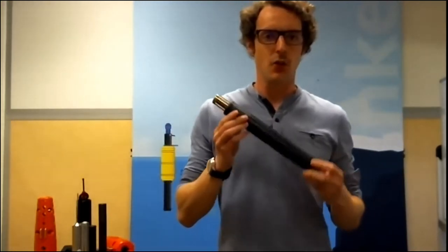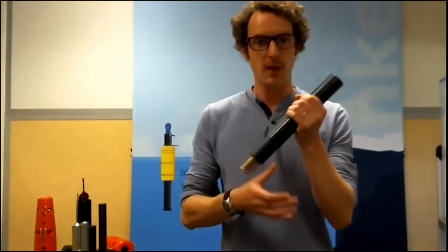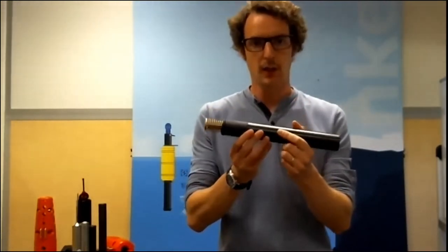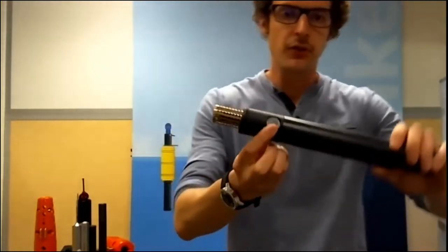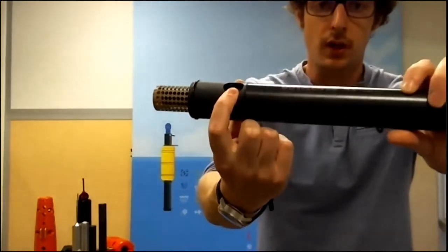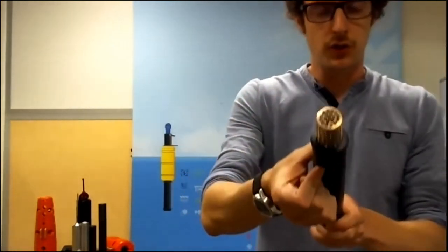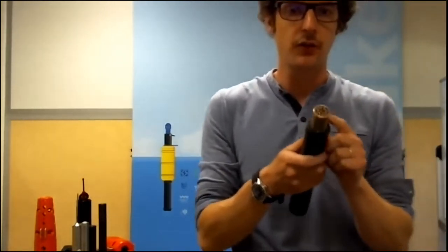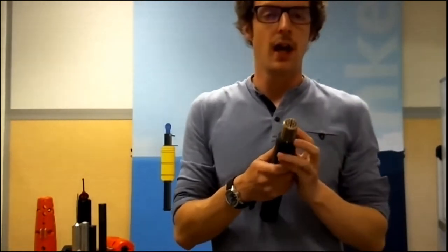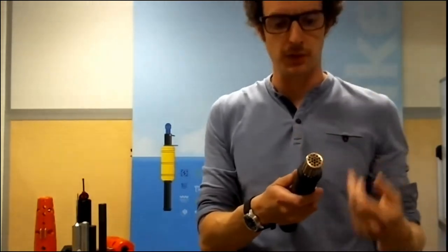Then we have the Ysense CTD. So as you can see, we remain on the same small and compact diameter, but then the top part is a little bit longer. So the depth sensor now is on the side, and on the front side, I have first a protective cage. So this cage has 2 purposes. The first one is to protect the sensor from any shock, and the second one is to prevent from biofouling. So it is a specific copper hollow cage that does not impact the measurements.